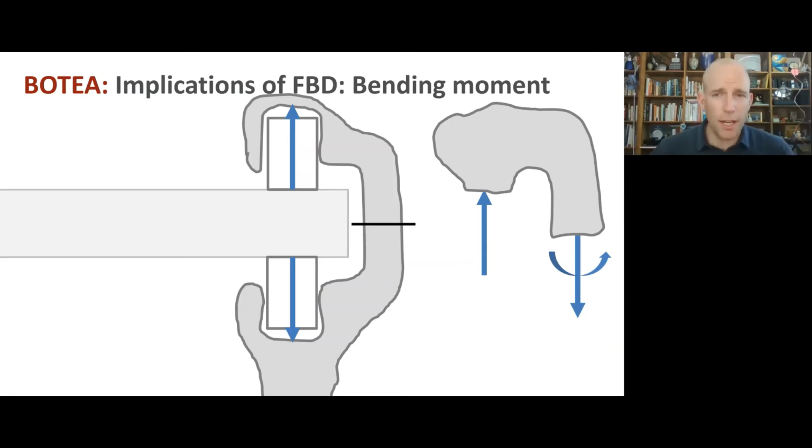Now, as we saw in many cases this quarter, we know that bending moments are bad for mass efficiency because they result in this uneven distribution of stress, and you need maybe a complicated structure to maintain a reasonable amount of mass efficiency despite the moment, or you end up with a lot of material that is not really carrying its own weight.